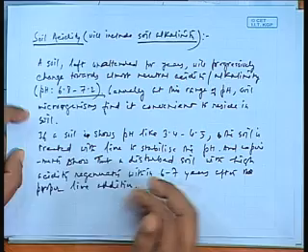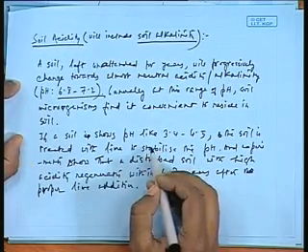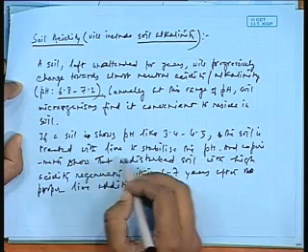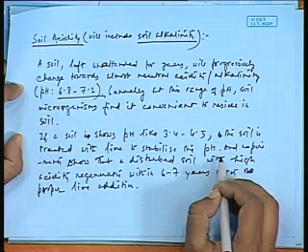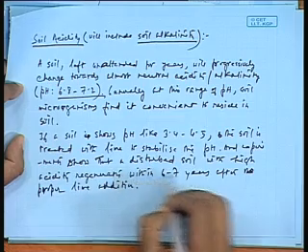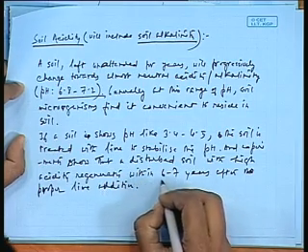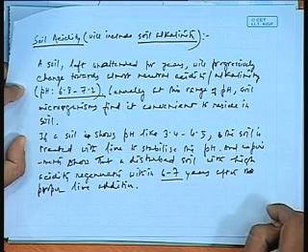If you could not write that down, we can still take it down. If a soil shows pH like 3.4 to 4.5, the soil is treated with lime to stabilize the pH, and experiments show that a disturbed soil with high acidity regenerates within 6 to 7 years after proper lime addition.